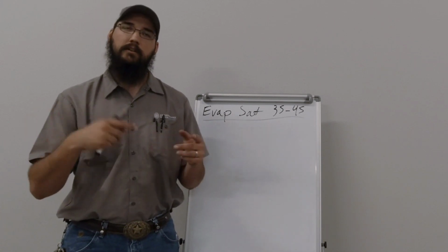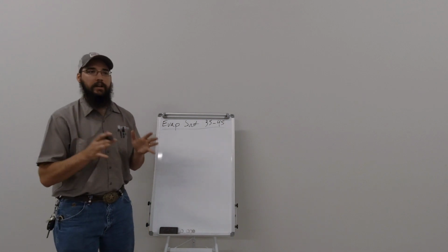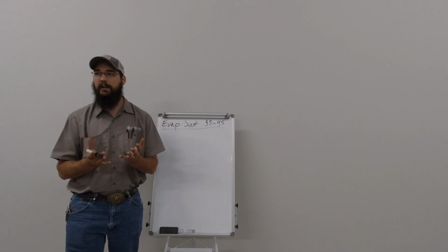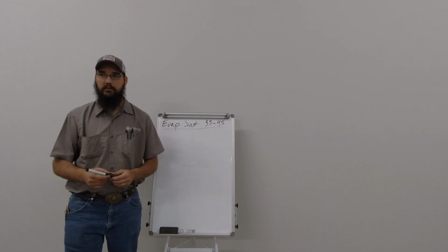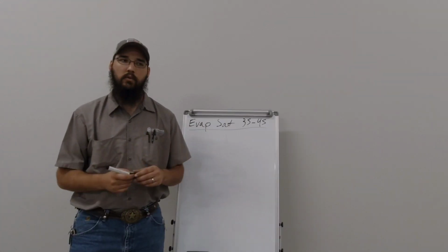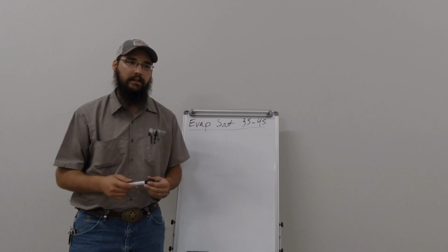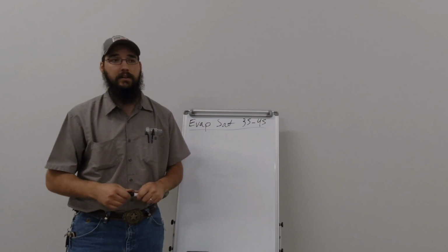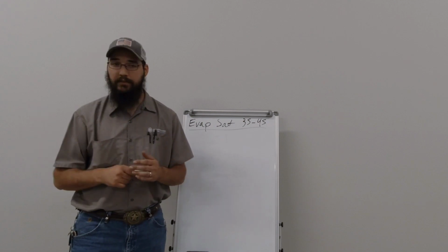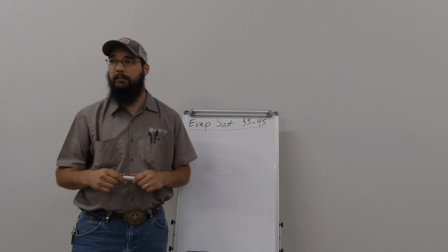It's something like that. The point is, it depends on the blend. With 410A it matters very little. You can accidentally use the wrong one and you're going to see such little impact. It's not going to make that big a difference. It literally, in some cases, may be 1 or 2 degrees. That's it. Where a 407C, it's 10, 12 degrees in some cases.